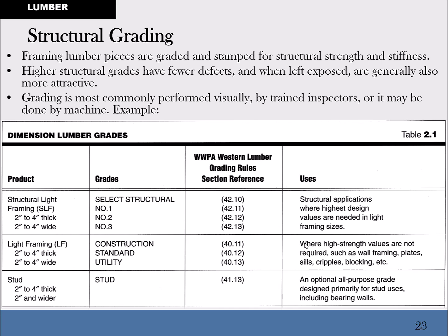So they also make studs that are cut just right so that you will get an 8-foot wall in the end when you include the 1.5 inches on the bottom of the stud or the bottom plate, and then the 3 inches up at the top for the top 2 plates for the framing. And so stud means that it's been cut to a precise length. And so that's an important